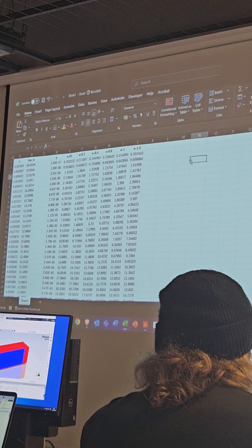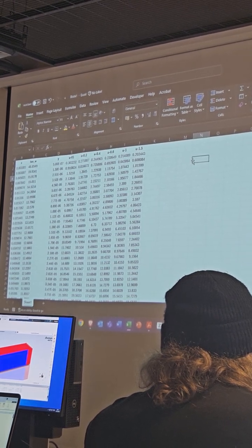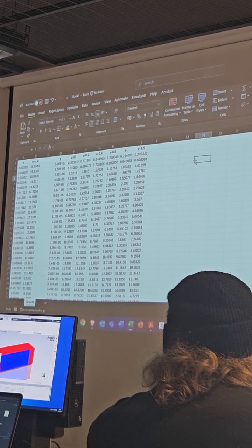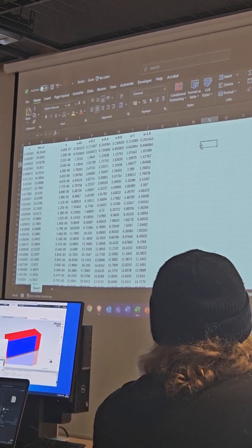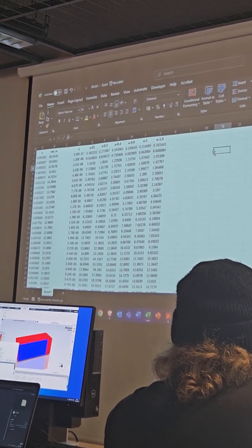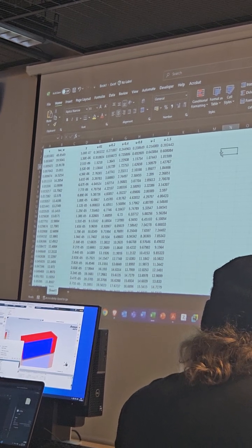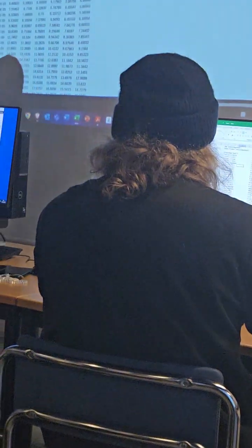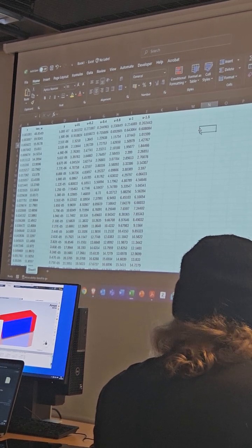There, theta is this integral. So that basically is the sum of the delta theta along the line perpendicular to the plate. So the delta theta is u as a function of y over u infinite, where u infinite is the free stream velocity, times 1 minus u y over u infinite, times delta y, that is the cell size, or the distance between the 2 points along the line.